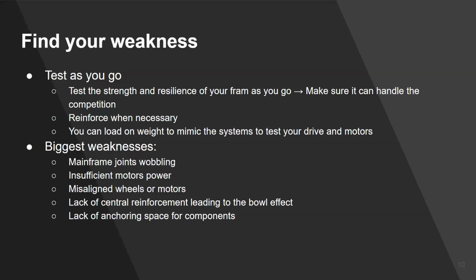And the last one, and it's something that I've noticed a lot in teams who do things separately. So teams who say, okay, you take care of doing the drivetrain, I'll take care of this system, I'll take care of that system, is when there's that lack of communication, the frame tends to be lacking in space for anchoring the components.